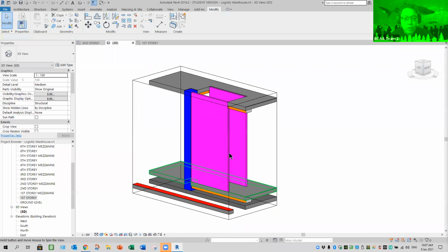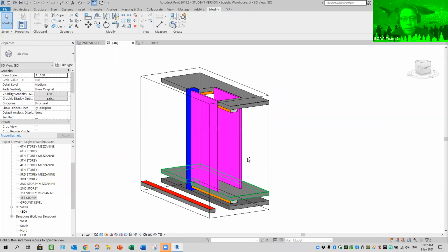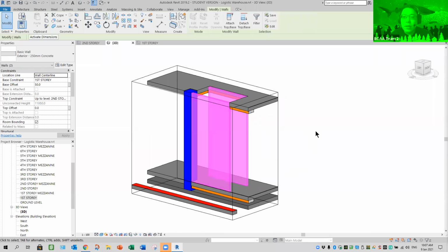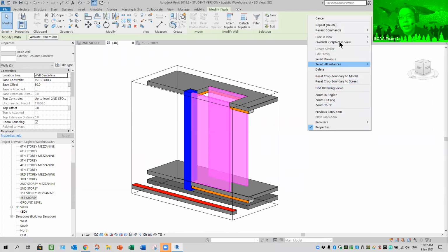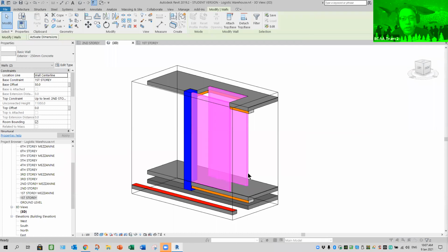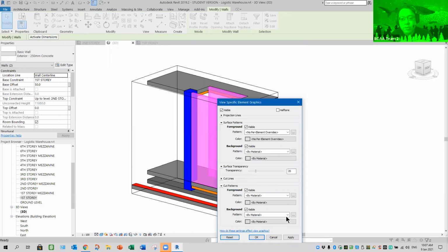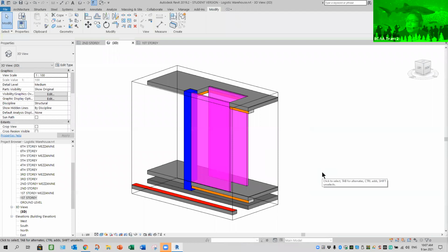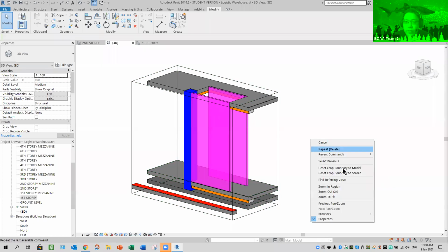Now, these two walls, I temporarily like to set the component not hidden, but highlighted as a bit transparent, so you can see the stairs being created inside. It looks like this. You need not hide away the wall just to see the staircase. But some of them might think this is a bit troublesome because transparency can create confusion. So don't worry, I have another method.